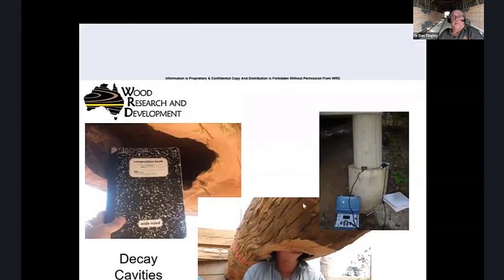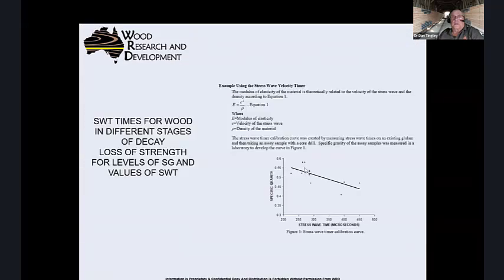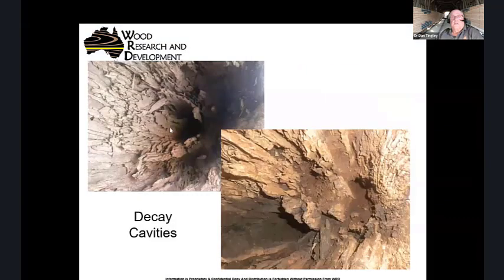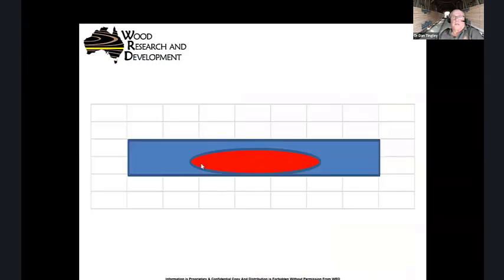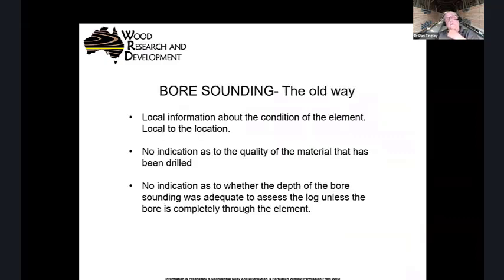That's Lori with his head up inside it, because we're able to moisture content test these pieces, use a stress wave timer, find these bad actors, looking inside here and here, and here's what caused it. That's the vertical, that's the bottom, and that's what it looked like. And so if we're not using inspection techniques that help us find these bad actors and know how to fix them and not design the same way again, then our timber bridges become a burden to our communities.